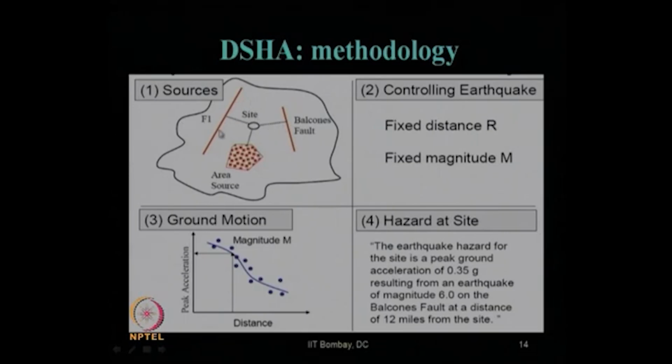You have to identify all those faults, that is, what are the sources of earthquake, from past historical data, and if it is a plate boundary, from the tectonic plate movement. From plate movement theory, you need to find out their magnitude, and from the fault characteristics, everything you need to find out after identifying the faults.